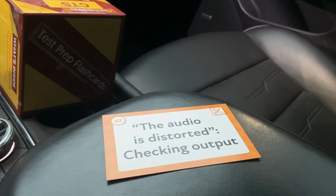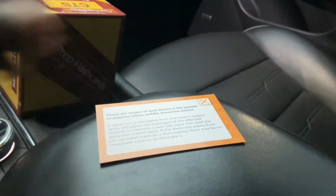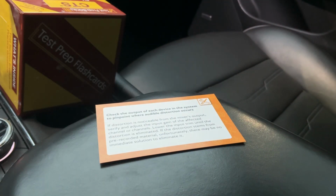The audio is distorted, checking output. Check the output of each device in the system to pinpoint where audible distortion occurs. If distortion is noticeable from the mixer's output, verify and adjust the input gain of the affected channel or channels. Lower the input trim until the distortion is eliminated. If the distortion stems from pre-recorded material, unfortunately, there may be no immediate solution to eliminate it.